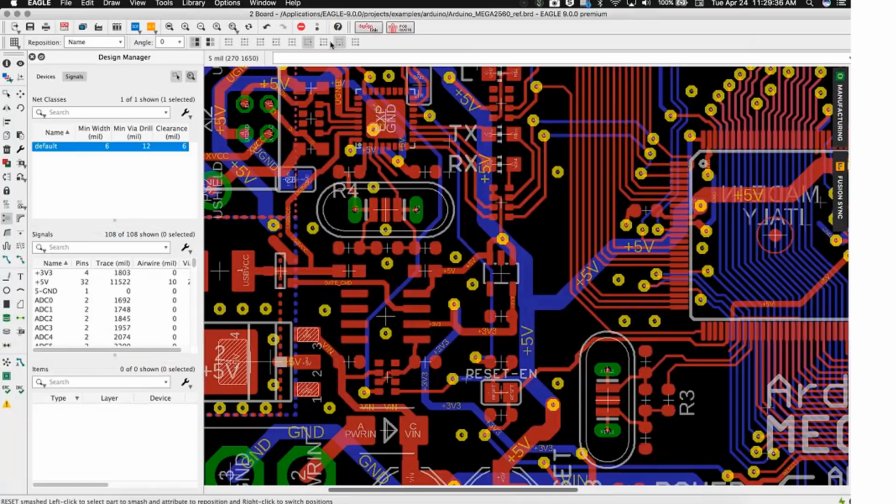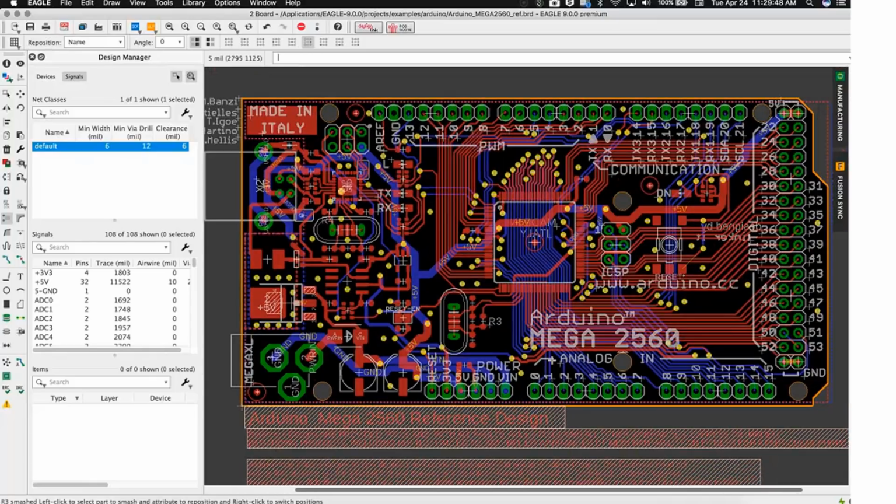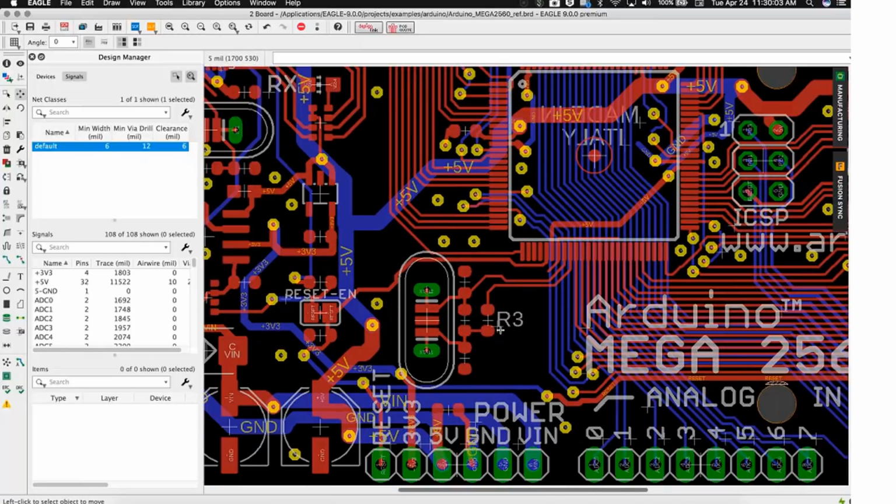So the nice thing is that if the components have a very similar geometry, something like resistors, capacitors, that sort of thing, you'll find that the text will align very closely adjacent to those things, and it'll be consistent for all of those parts. So a lot of that time that you spent going in there and using the move tool and slowly saying, well, I want this designator to be right here, and the adjacent designator over here, I want to try to get those two things lined up. All of that is handled for you in a simplified way. And it can be applied to a group of objects as well.